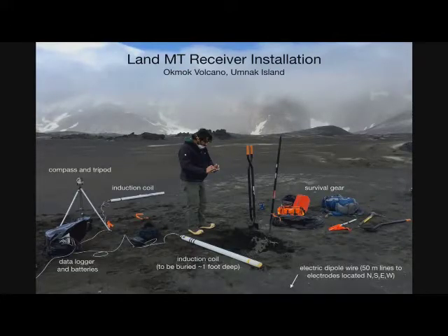On land, the impedances of these systems are really high, so that you're not actually drawing current from the ground, and that basically makes it an inherently noisier measurement. So you get around that by using longer dipoles. The electric field that we measure is in volts per meter, so every meter longer your dipole is, you get a bigger voltage.